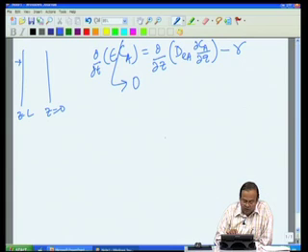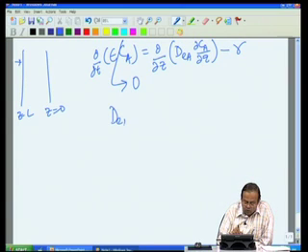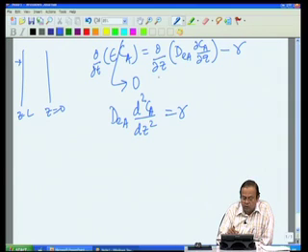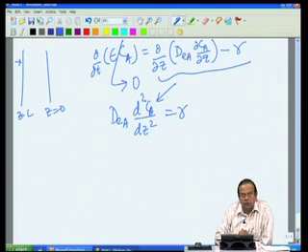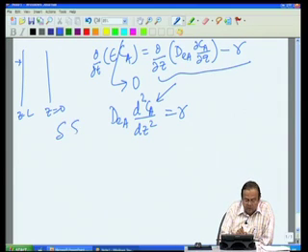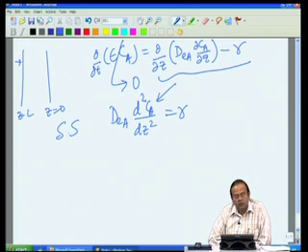So, we have a steady state balance, and the partial differential equation now will convert into an ordinary second order differential equation, and we will also assume that DEA is constant. So, we will get, from this equation, the steady state version. So, this is my steady state mass balance equation for diffusion reaction.